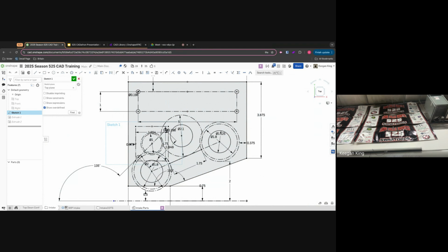Cool. So you're going to have to break one of the dimensions, one of the tangents on this circle, preferably the center. Yes, break it. Press on it, press backspace. You move the circle up to the other side of this, and then tangent it again. Okay, and then you grab this construction circle again, and then the circle there. Okay, OnShape is an interpretive language.